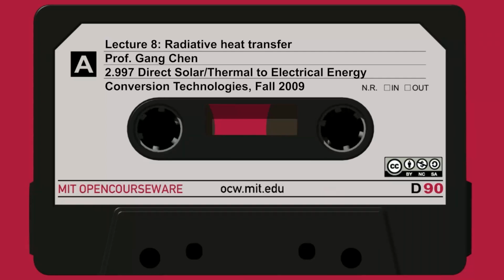Of course, this has a lot of engineering aspects. Suppose I have this ideal selective surface, with absorptivity and emissivity. On the other side, you can hardly design a surface with really zero emission, so this side will lose radiation.